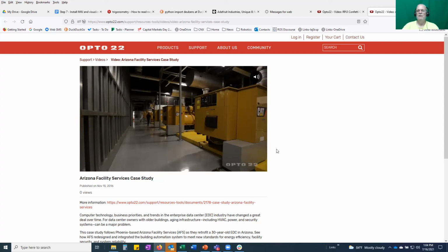So they go down these little pathways, and in my opinion, they're going to get themselves in trouble by doing that. I mean, in your opinion though, isn't CAN a better solution? If you're going to run long distance in a noisy environment, CAN is better. RS485 is better. There's probably even USB. I think USB is a differential interface. So probably any of those are going to be better than I²C, which was designed to connect two chips together side by side on a board with pull-up resistors. So they weren't meant to run several feet or in a noisy environment.